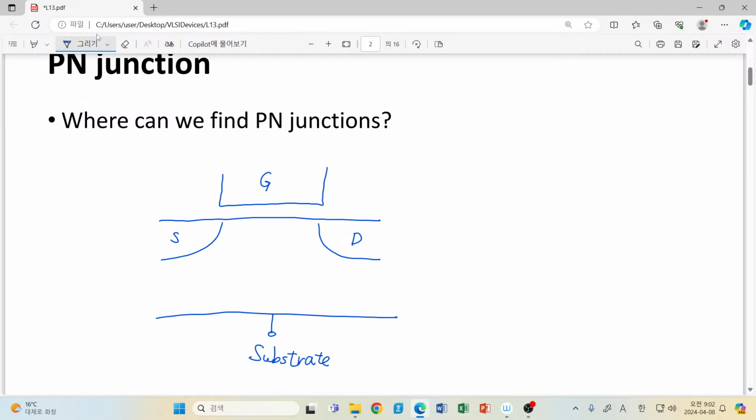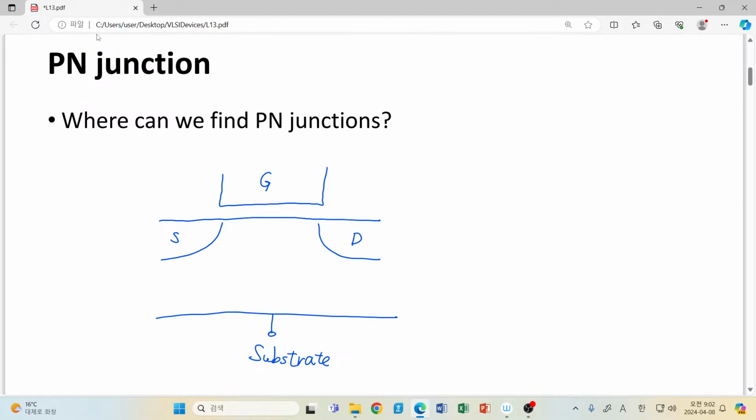In the case of an N MOSFET, where electrons are the moving charge carriers, we introduce an N++ region, which has really high doping density, in source and drain. So basically we have a lot of electrons which try to conduct.